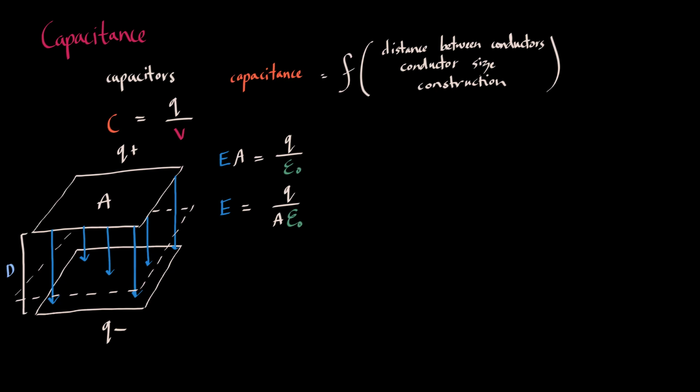It is clear that all the field lines running from positive charge to negative charge are normal to the surface. Because the field is constant across the distance d, our integration to find the voltage difference just becomes multiplication with the electric field vector. Now that we have the voltage in terms of the capacitor geometry, we then substitute into our formula for capacitance. Here we confirm that the capacitance of a parallel plate capacitor increases with its plate area A and decreases with its plate-to-plate distance d.